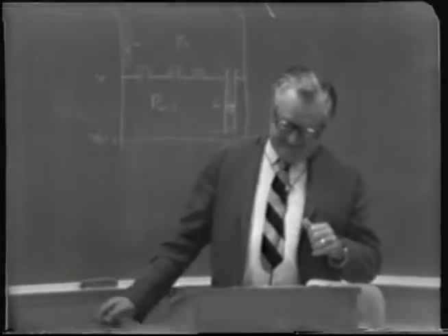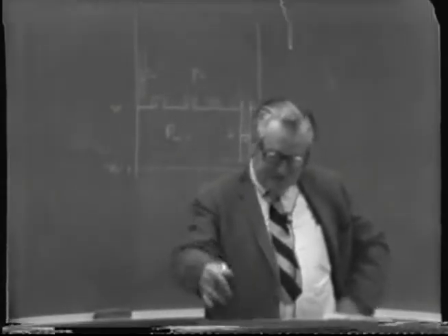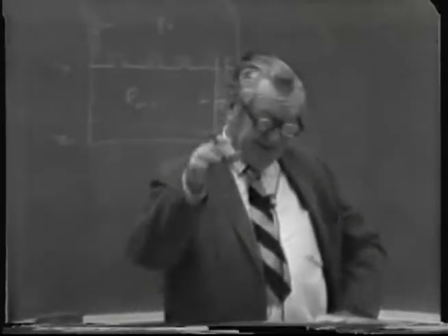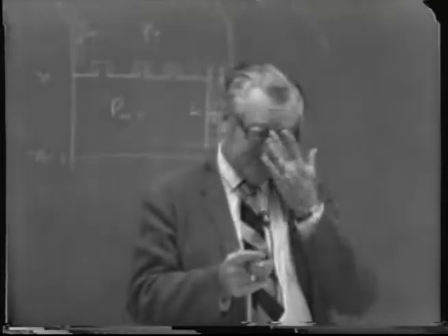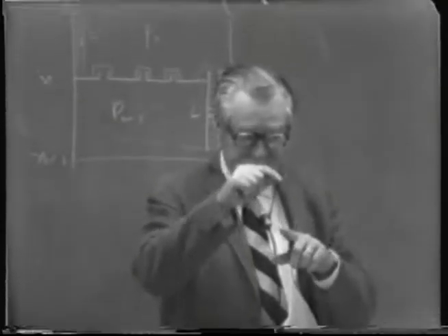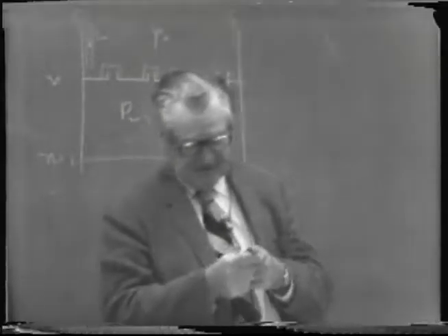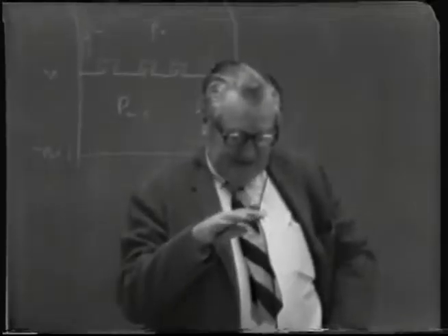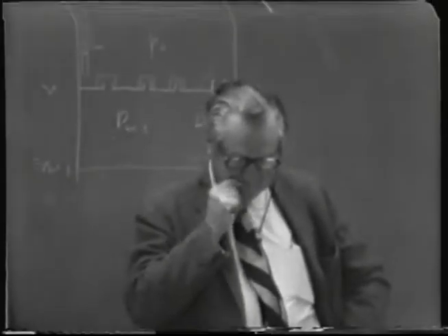Generally speaking, the tubes empty into a little seal cup at the bottom, and you have to have a certain amount of clearance between the bottom of the tube, or whatever the downcomer is, and the seal cup, so it can flow across the tray.